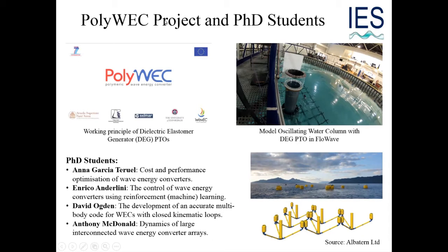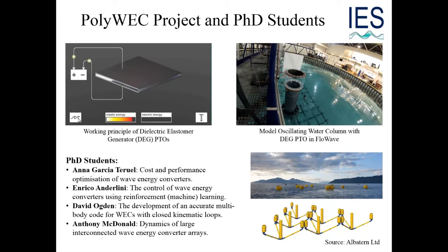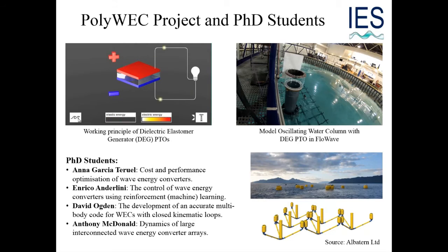The other thing that David briefly mentioned was this Polywec project, which David leads and which I work on. Just to give you a very quick idea of what the Polywec project is, it's using elastomers. Basically your power takeoff now becomes this elastomer, which is just a rubber material. You put electrodes on either side, top and bottom of it. When it's fully stretched, you charge those electrodes. As it relaxes, it pulls the electrodes apart, the voltage increases, and you discharge and you can get more power out.